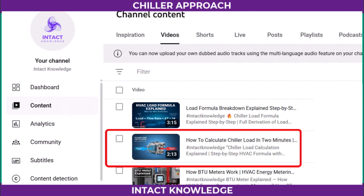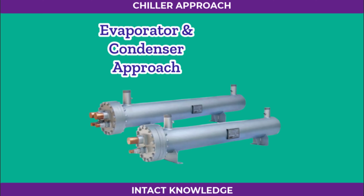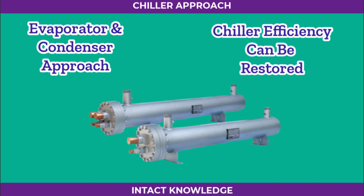In our previous video, we discussed how to measure chiller efficiency. If the chiller's efficiency is found to be low, then we need to check the approach values of its evaporator and condenser. These approach readings help us pinpoint whether the issue lies in the evaporator or the condenser, and by correcting that problem, we can restore the chiller's performance.